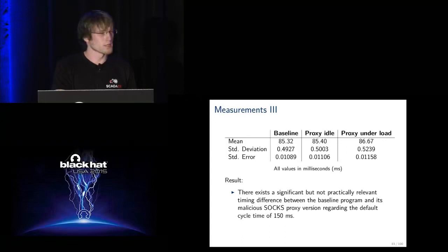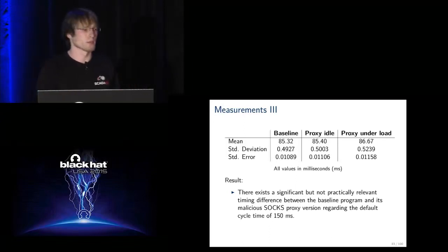But if we take the maximum default cycle time of 150 milliseconds, that fraction is only 1%. And in this case, it's not very likely that we will hit this maximum cycle time and put the PLC into an error mode.